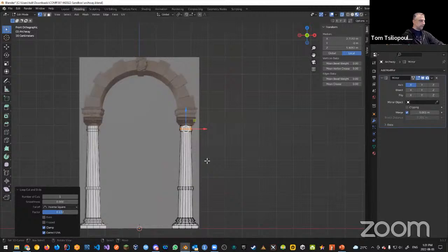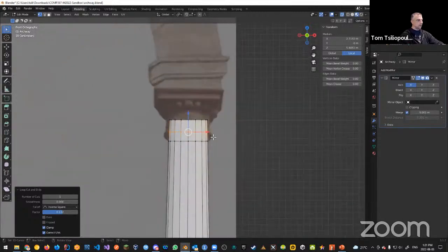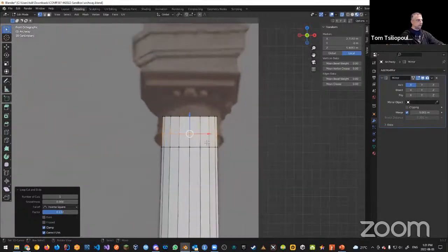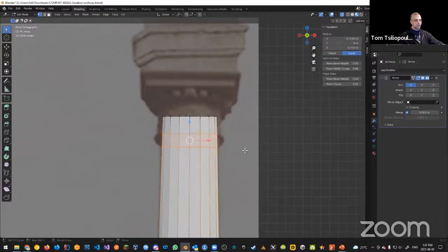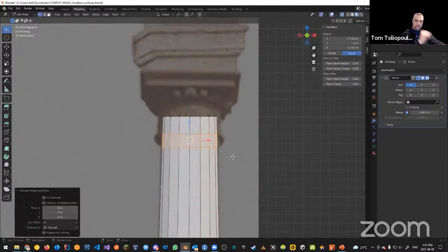Again, if I look at it from the front, we can align it if you really want to. I'm just zooming in here, so you can see that this is the case. Then I can deselect all, box select that part, just like we've done in the past. Same process, nothing different. Then I can extrude and press enter, which creates additional geometry around everything.